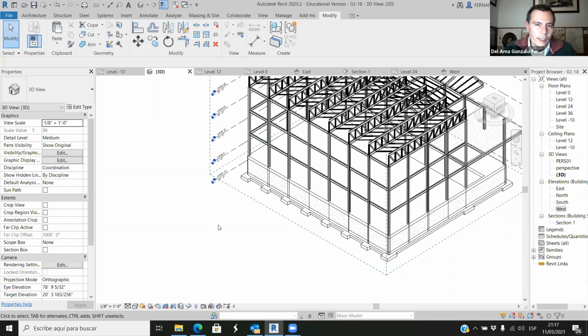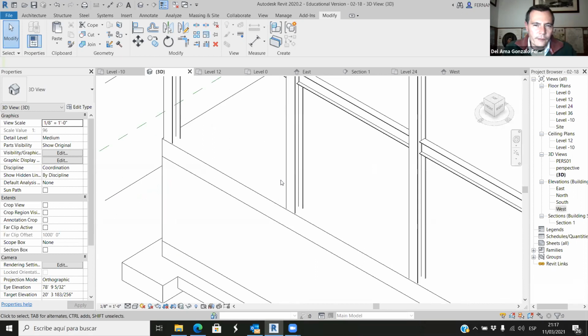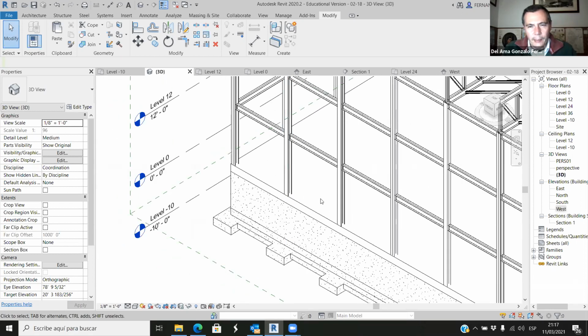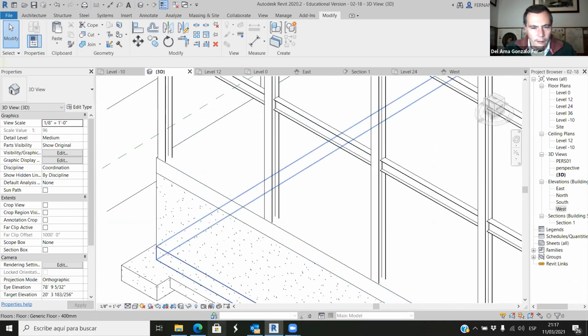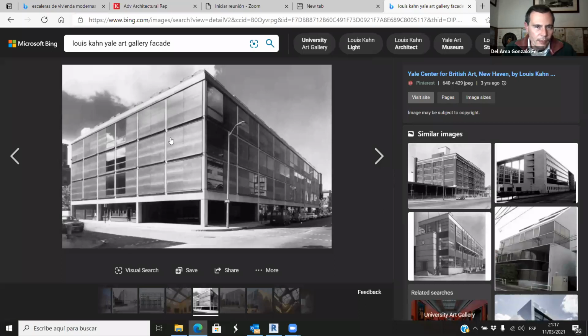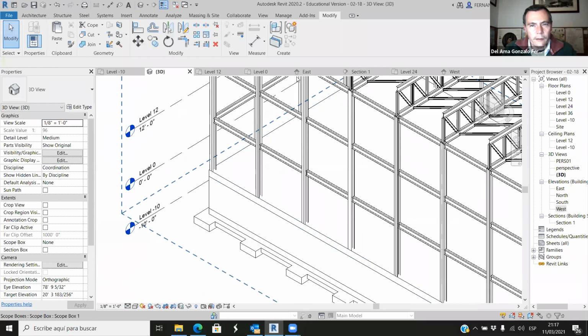so now I'm going to create a wall with different parts, keeping in mind that I want to see the structural elements like this. Okay, so the wall is not going to go from this point to that point. I'm going to fill just each rectangle with that wall. So let's try to do this from level 0.